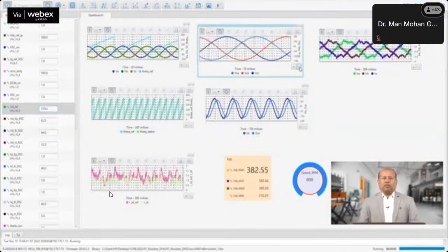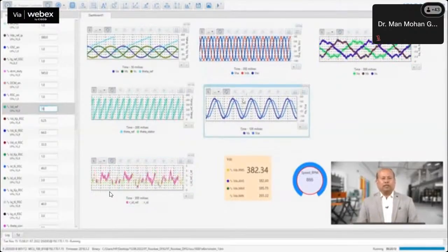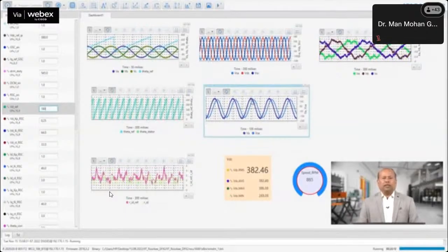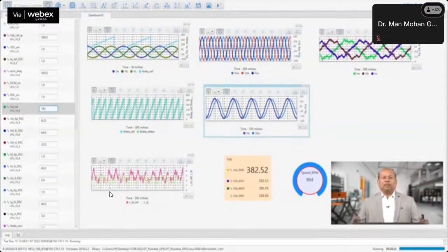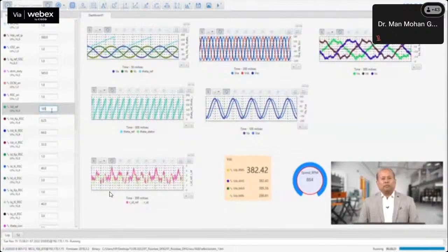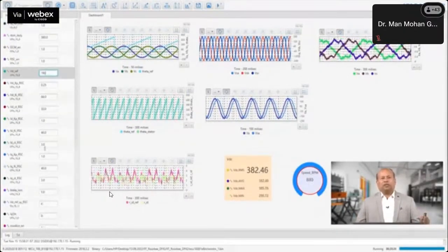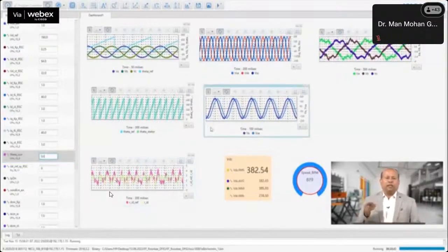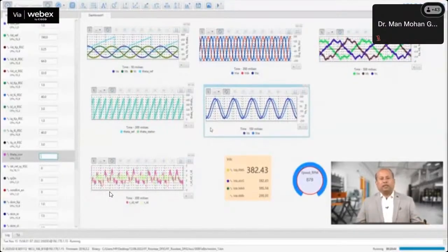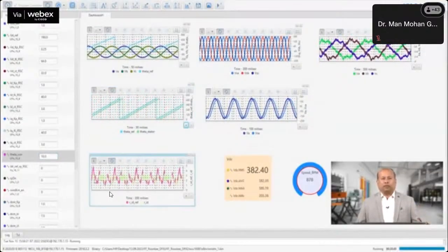In this process, we also observe that the rotor current is also increased as it takes current from the grid to build the stator voltage, as from the relation the stator power is 1 by slip times the rotor power.